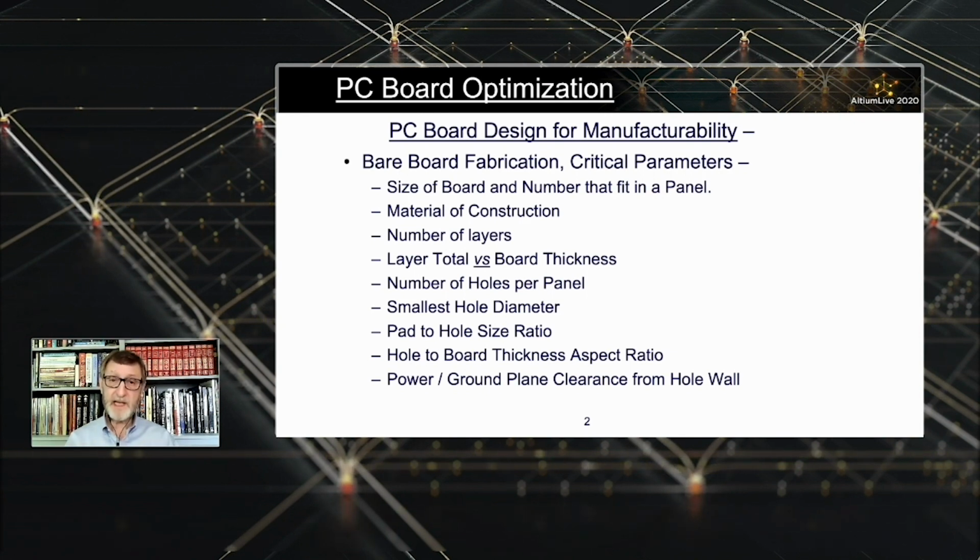Those are just examples of standards you, as a designer or an engineer, if you're designing circuit boards, need to be familiar with. So keep all that in mind. If your company's not an IPC member, try to get them to be. If not, then just buy the standards directly from IPC. You'll pay more if you're not an IPC member, but they're still very reasonably priced. I mean, anywhere from $20 to $50 each, and that's not outrageous, given that you probably only need a half dozen or so. So think about that very carefully.